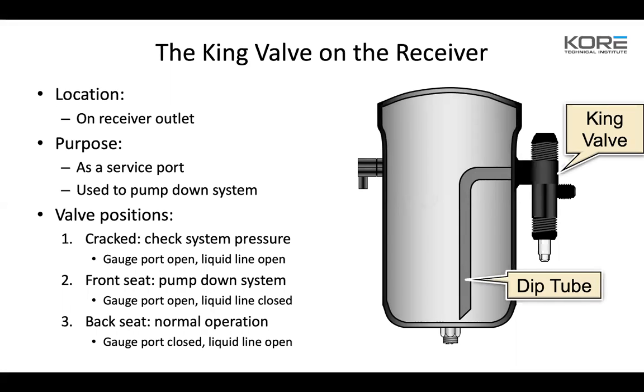We've talked about this too, guys. Please never, never, never put a pair of channels on that valve stem. And please don't use a crescent wrench either. There are two sizes of service valve wrenches that you can buy: the bigger ones for the rack systems, and one general one that does 90% of your smaller systems. Make sure that's part of your arsenal of tools. I've seen guys look at me right before they go for their Leatherman and I'm just like, don't do it. Don't put teeth marks on those valve stems.